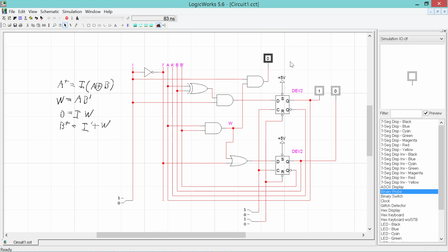The key to understanding the state machine behavior is to understand that only when clock goes from 0 to 1 does the output mean anything. Otherwise, the output value or output values, depending on the state machine implementation, could be changing in the middle. They could be in the process of changing and are hence invalid until the system clocks from 0 to 1 on the clock input pin.